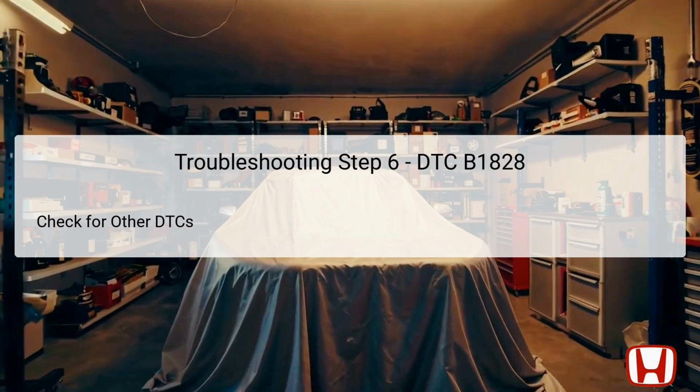In this troubleshooting step, continue by checking for additional DTCs including B1825, B1826, and/or B1827 using the HDS. The identification of any of these codes may suggest underlying issues in the power seat adjustment system that may have a direct correlation with the initial DTC B1828.